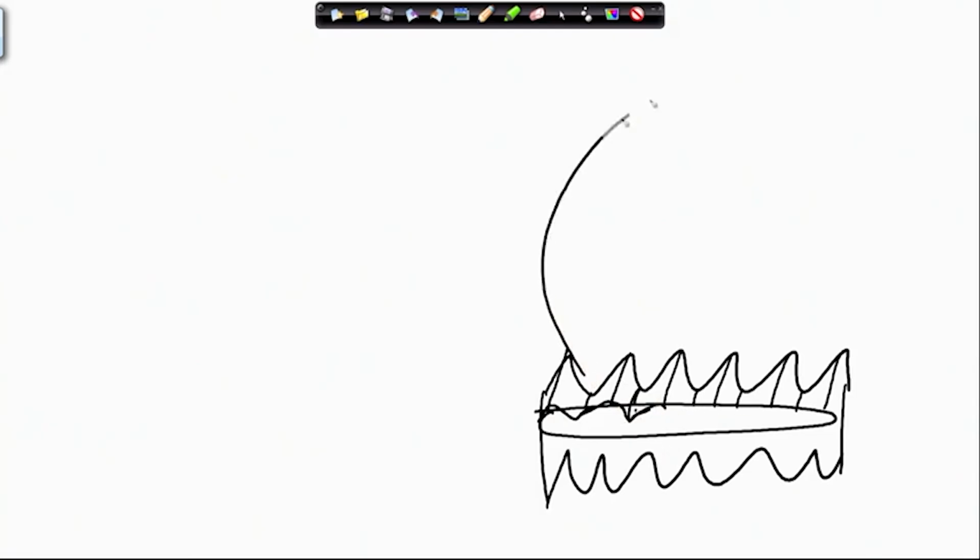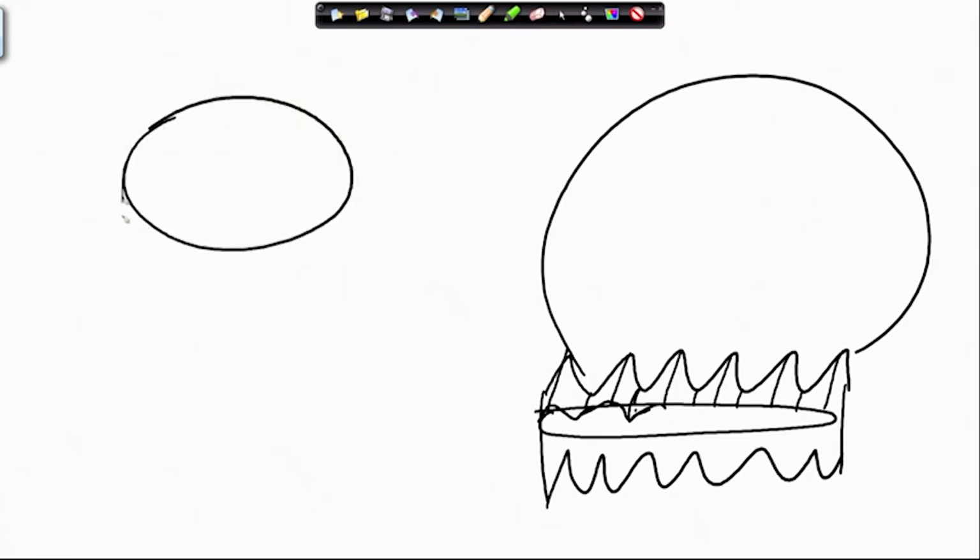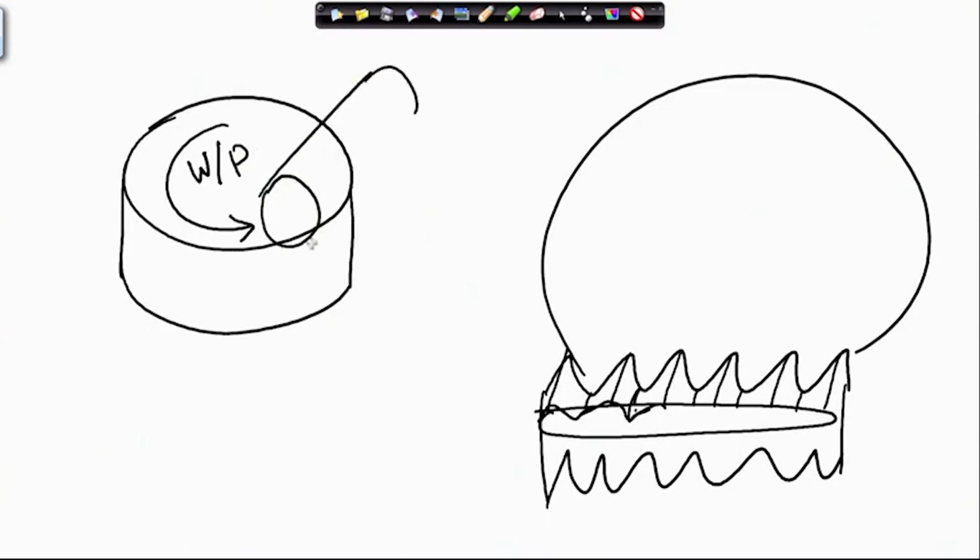So, as it is sharp, now it can engage with a hard cylindrical body and remove those materials which do not belong to it and cut it away. But for this, we need to give it certain types of motion. What are these motions? First of all, if I have the cylindrical body, I need to rotate it. So, this is the work piece now, it has to be made into a gear. This is the worm which we were talking of being used as a cutter, and it is given a name called hob. The hob is a worm with cutting edges.